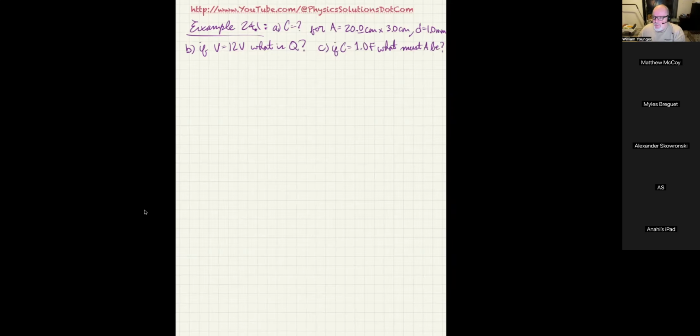Okay. Now we've already derived an expression for the capacitance of a parallel plate capacitor, which is what we're dealing with. So I'm going to make use of that, and I'm going to give you a little information as well. So the capacitance was C equals Q over V, and for a parallel plate capacitor, that turned out to be epsilon zero A over D. One thing I will tell you is that basically this is the result for two plates being separated by a vacuum.